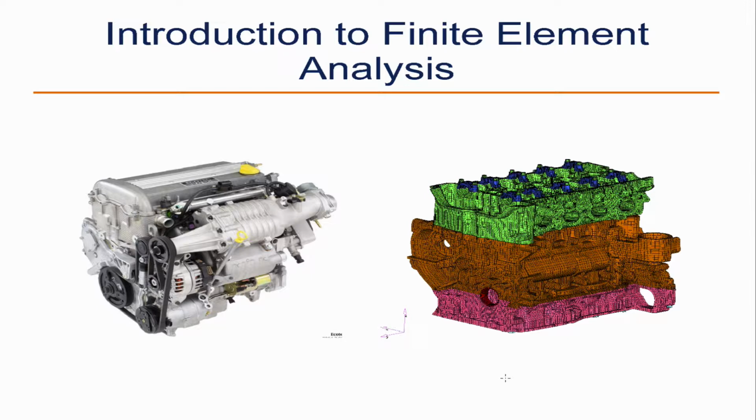Okay, I do that right from the beginning, so I never look at this as matrix methods and structural mechanics. Finite elements are a way to solve any partial differential equation boundary value problem, and the physics doesn't matter. If you have a partial differential equation, it's possible. It doesn't matter if it's a heat transfer problem, a mechanics problem, a diffusion in porous media problem. If you just follow the same steps, and we'll talk about what those steps are, you can use essentially the same method to solve all of those problems.